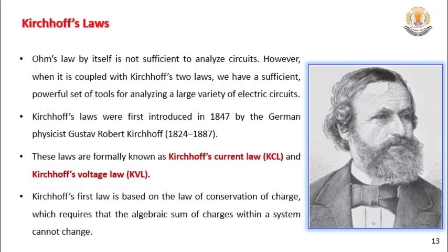So to apply KVL, you should have a closed loop. To apply KCL, you should have a node or part of a circuit. I will explain later, but let's start simply like that. And you can write it mathematically.